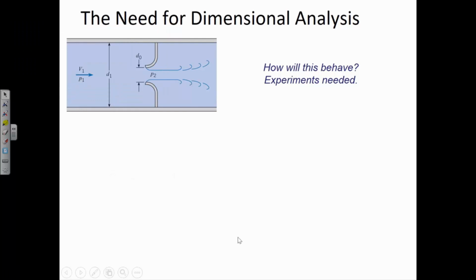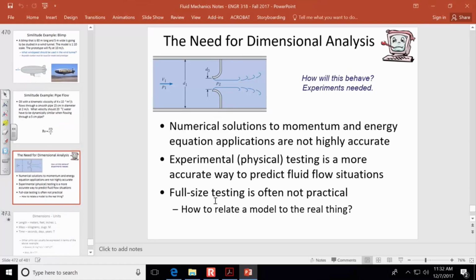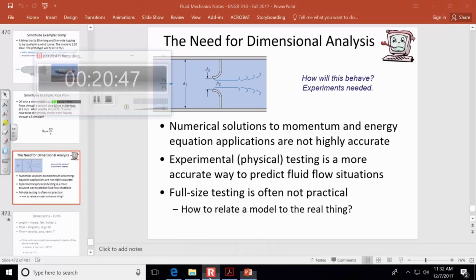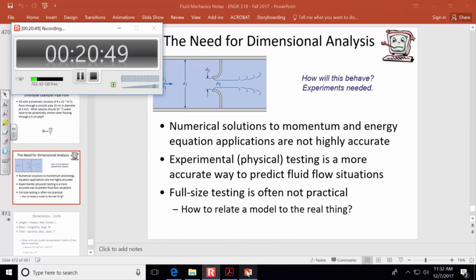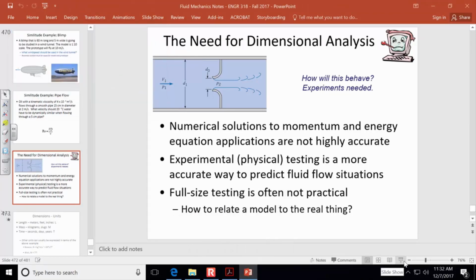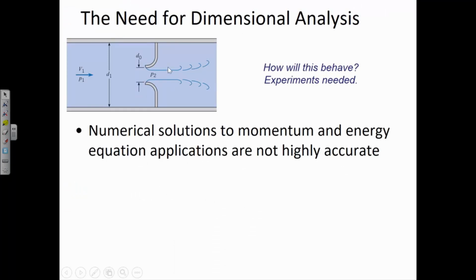All right. So as I was saying, what's pictured here is water flowing through an orifice that's inside of a pipe, and the water is going in the opposite direction that you'd normally expect water flowing through an orifice like this. And so, if we wanted to understand the head losses through such an orifice inside of a pipe where you've got full flow, you'd have to do some experiments, and you could create a series of experiments to increase the flow rate and measure the head loss through a fitting like this.